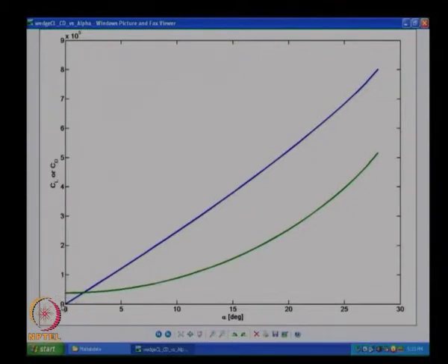And the lift is going to be 0 at 0 angle of attack, and it is going to increase almost linearly up to some point, and then it becomes non-linear after some time. You can talk more about why it becomes non-linear. You will suddenly see that the flow is jumping from shock to expansion. All that will start happening. This is where it starts going non-linear. Around here is when the shock becomes a Mach wave and becomes an expansion.